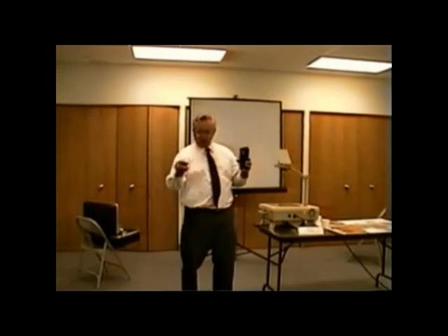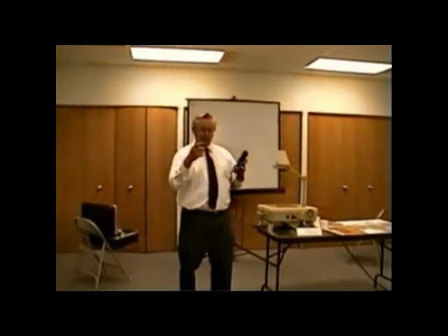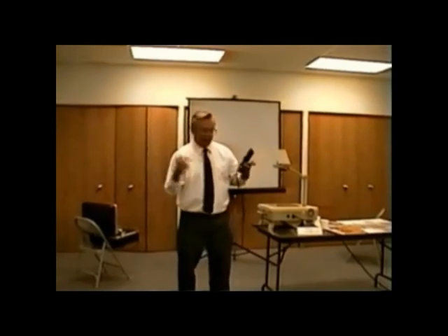Well, that's your 5-second safety. The board is not seeing that. The board is not seeing microamps. So I says, well, if you had 0 microamps, I would say that you got a ground wire that is cut, or the furnace is not grounded.